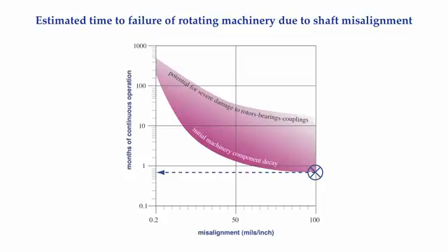will begin to see what we call initial machinery component decay. We will begin to see some damage to the bearings. We will begin to see some leakage at the seals. We will begin to see some wear in the coupling and begin to cyclically fatigue the shafts.